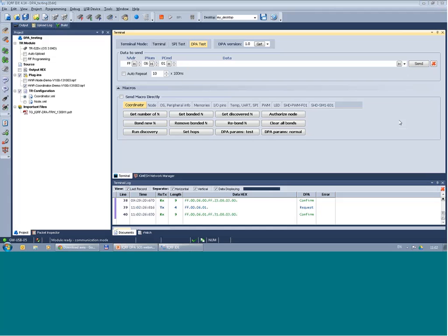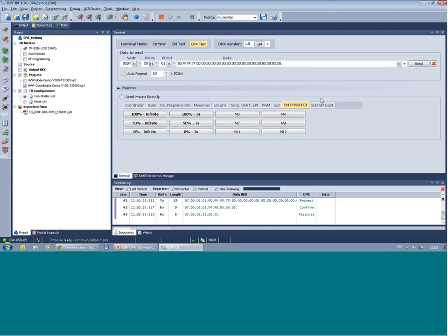If you cannot see it, I can also switch on the lamp. I have a module here, so I will put it on infinite, 50%. I'm now controlling the PWM through actually writing into the RAM, and I send it, and I hope that this time you will definitely see it. So on your webcam, you see that the light is now shining. And now you can control the whole network immediately like this, if you want to read the temperature, or if you want to control PWM, and so on and so on.